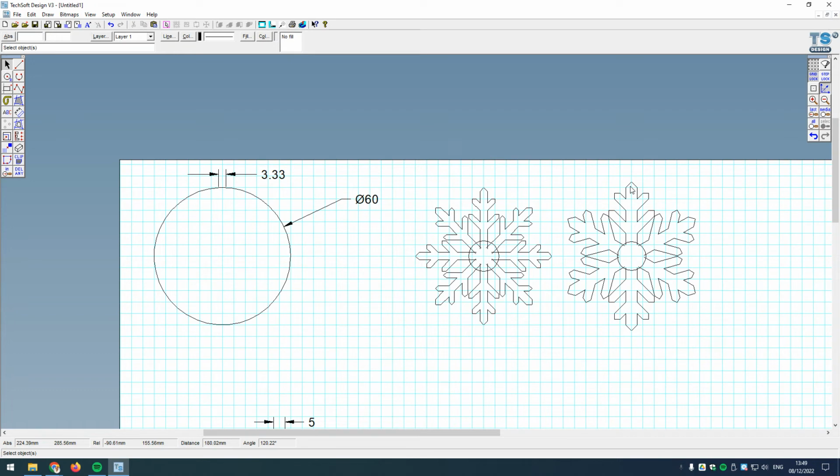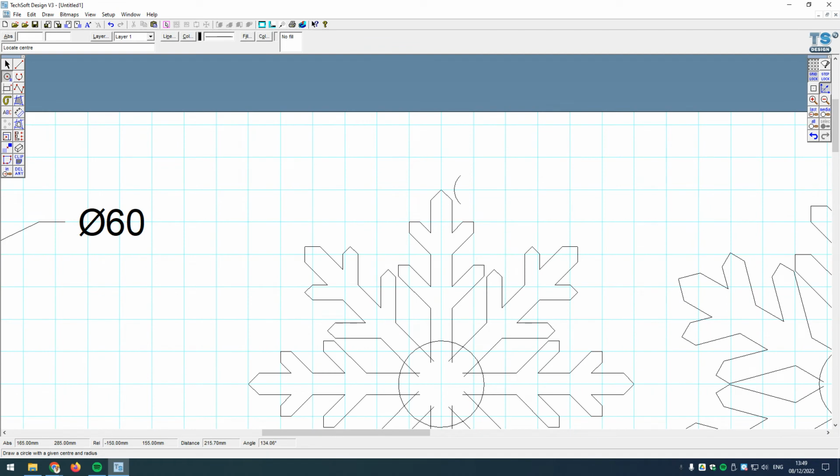And secondly, I'm going to look at color coding it for laser cutting. Okay, so for the little circle here, first of all, let's get the circle tool. And I need to think about how big this little circular cutout at the top needs to be. Hopefully it's going to make sense when I do it. I'm thinking of making it 7.5, no, 6, let's make it 6 millimeters in diameter. So 3 millimeters radius. I'm going to come in here and I'm going to draw this.